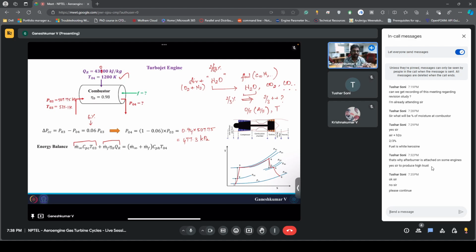Now, once it burns, H2O will be in a gaseous state because the temperatures would be very high. So if you consider that state, if you see the energy difference between the inlet and the outlet, then you will have lower energy release because your H2O is in gaseous state.